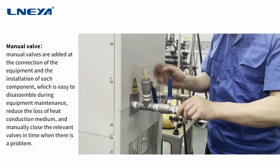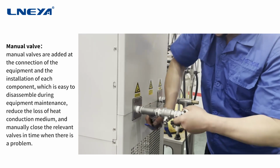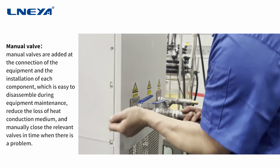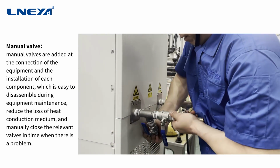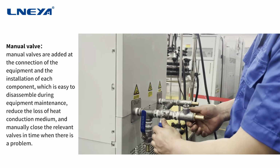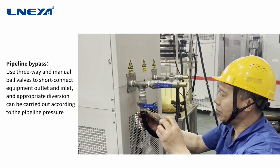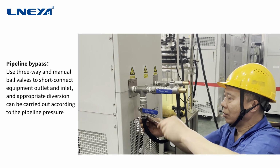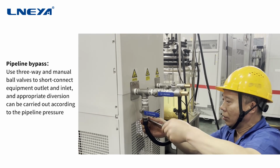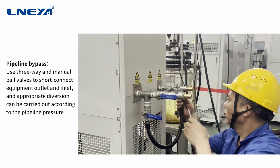Prepare the valves. 1. Manual valve. Manual valves are added at the connection of the equipment and the installation of each component, which is easy to disassemble during equipment maintenance, reduce the loss of heat conduction medium, and manually close the relevant valves in time when there is a problem. 2. Pipeline bypass. Use three-way and manual ball valves to short connect equipment outlet and inlet. An appropriate diversion can be carried out according to the pipeline pressure.